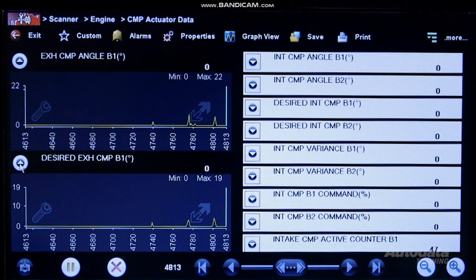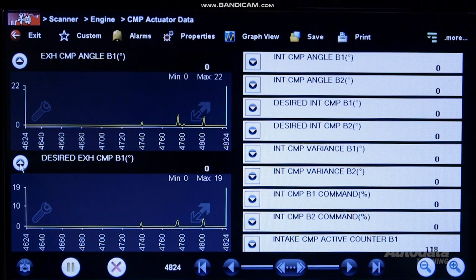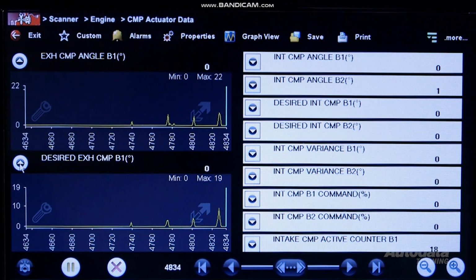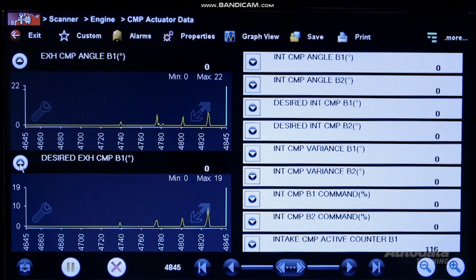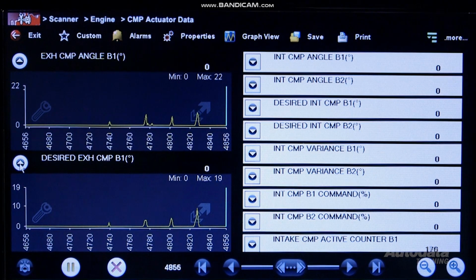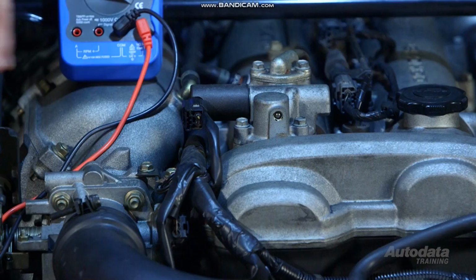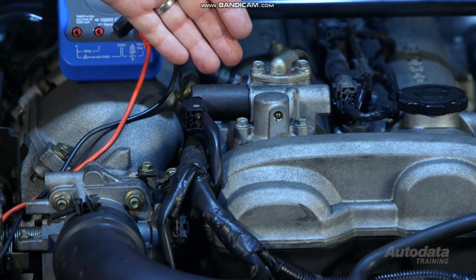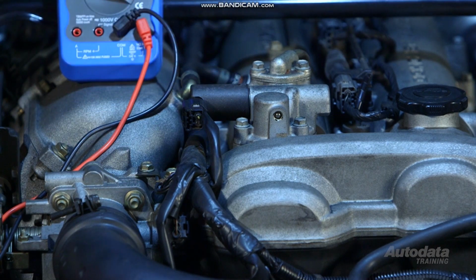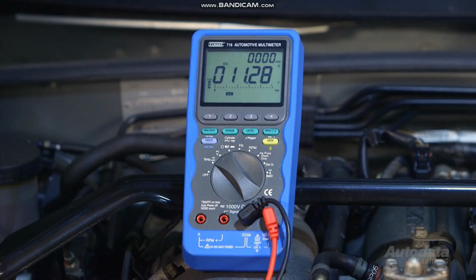Using an oscilloscope is another way of confirming that the information is reaching the actuator. This, however, will not tell you if the data is correct. A fault could be in the module, the wiring, or the actuator. If it's determined that a fault exists, it will be necessary to carry out the following procedures.